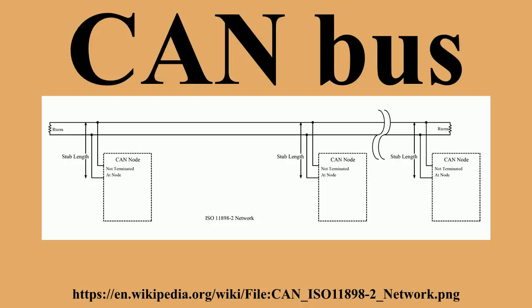The CAN specifications use the terms dominant bits and recessive bits, where dominant is a logical 0 and recessive is a logical 1. The idle state is represented by the recessive level. If one node transmits a dominant bit and another node transmits a recessive bit, then there is a collision and the dominant bit wins. This means there is no delay to the higher priority message, and the node transmitting the lower priority message automatically attempts to retransmit 6-bit clocks after the end of the dominant message. This makes CAN very suitable as a real-time prioritized communications system.